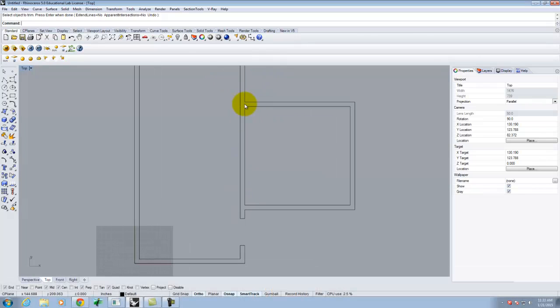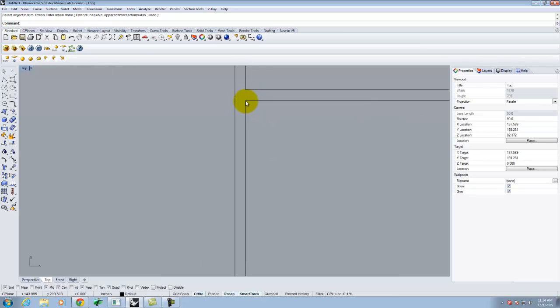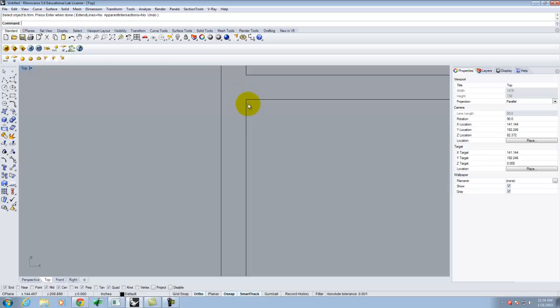I still do need to draw the door. And this brings out another thing that works in Rhino that I think is really important that you learn and get used to. And that is something that's called smart tracking. This is how you can specify a position in space without actually drawing anything. What I'm going to draw first is the little door that goes into the bedroom on the back. I want to cut that opening. It's not in the middle of the wall anymore, so I can't use midpoint. But I can assume that it's 3 or 4 inches from this wall, and I want to draw it out in this general region.